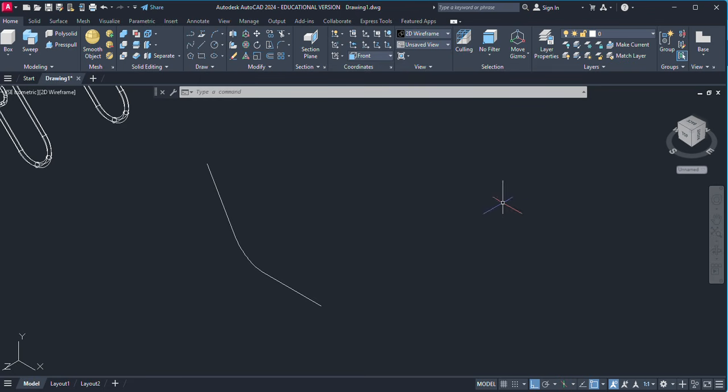Meanwhile, we are going to draw on this right side, so you change the coordinate into right. Here you have to change. Wherever you want to draw, whichever plane, that can be selected here. Accordingly, you can draw. So you take the line command, it is better.